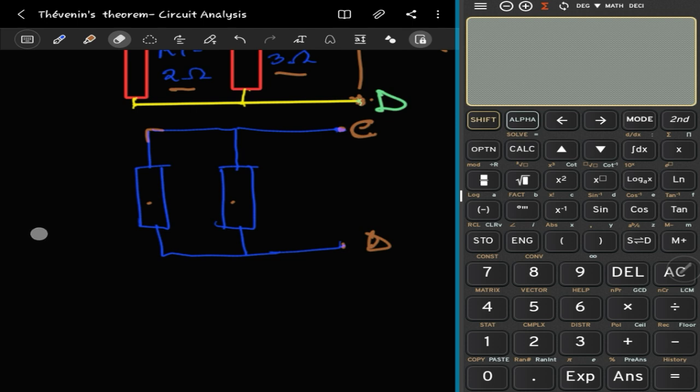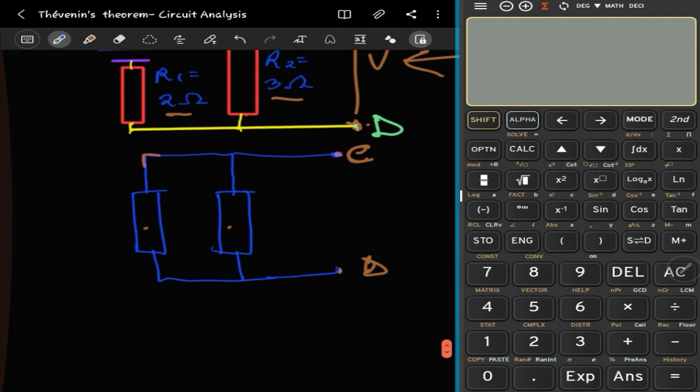If it's for 2, that's why we have product over sum. But if it's for 3, there's a formula for it. Because there are 2 here, we go straight for it. Product over sum. So the effective resistance here, which we basically call the internal resistance because we are looking at it from here. Anything else within this side is what we will consider internal resistance, which is a small r, right? So product, which is a 2 here, times a 3, all over the sum of these.